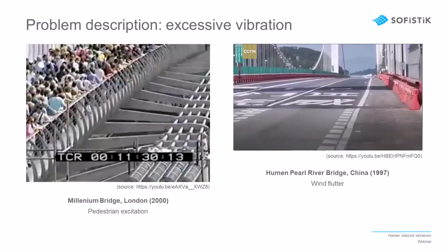Nevertheless, Millennium Bridge has received vibration dampers and was tested extensively, while the other bridge was left as is. So the excessive vibration is not dangerous, yet it is still unacceptable. The question remains why, and the answer is very simple: the limit of comfort within the human response.